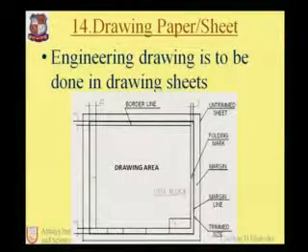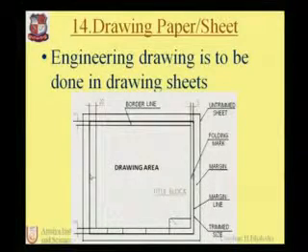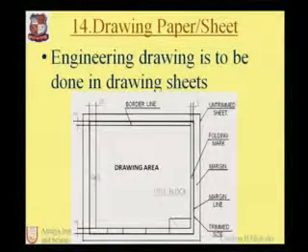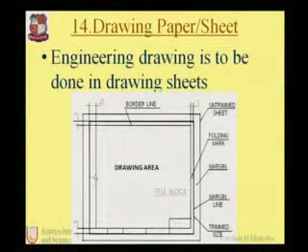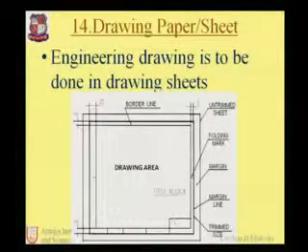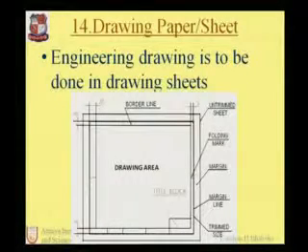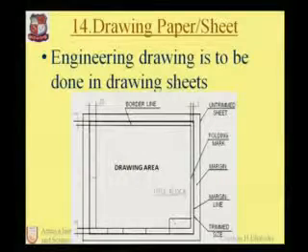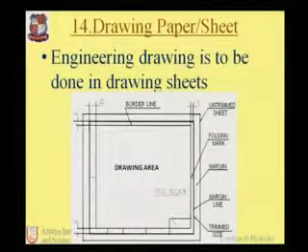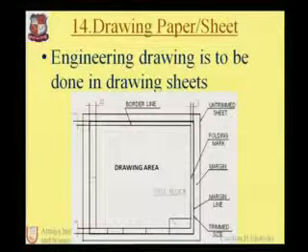Okay, on the left hand side, in the case of the trim size, this line indicates the dimension of the margin, which is 20 mm, as we see in the dimensions. And on all other three sides, a 5 mm margin should be taken. Now, what is the need of taking the margin? The margins are used for the proper drawing area work, so that the drawing should not go underneath or overlap the sheets which is used for drawing the quality work.